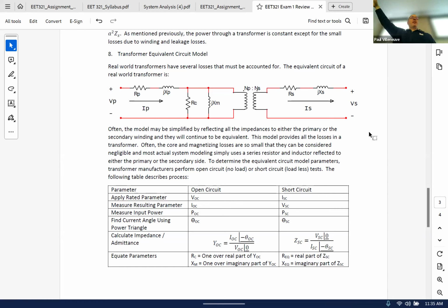like if you were on a transmission system that had, let's say, 50,000 amps of current at 345 kV. If you were to step the voltage down to, let's say, 115,000 volts, the fault current would be 3 times that 50,000 amps, 150,000 amps of fault current on the low side of the transformer. That would be very difficult to manage. That's a lot of fault current. Because the one thing about fault current is it doesn't care what the voltage is. The current is what does the damage. The voltage will just arc, but the excessive current will do that.